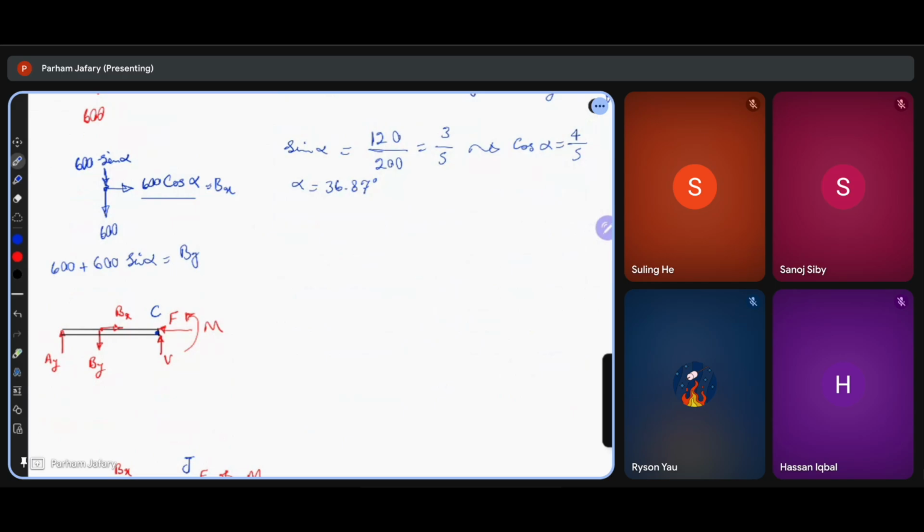Yeah. Because they're internal forces, that's correct. So when you want to calculate the reactions, you don't care about the internal forces, okay? Because they cancel out each other. But when I section my beam, then there is nothing to cancel out that force, and I have a force in the middle, which is the internal force, okay?